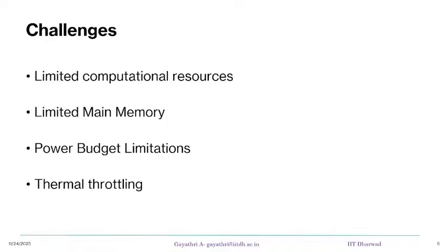So by default there is something known as thermal throttling, where you trigger some action to make sure that the temperature does not hit that limit, and if it is hitting, you immediately safeguard. In low resource, low form factor devices, you can hit the temperature very quickly, right? So how do you not have that happen in your SoC?